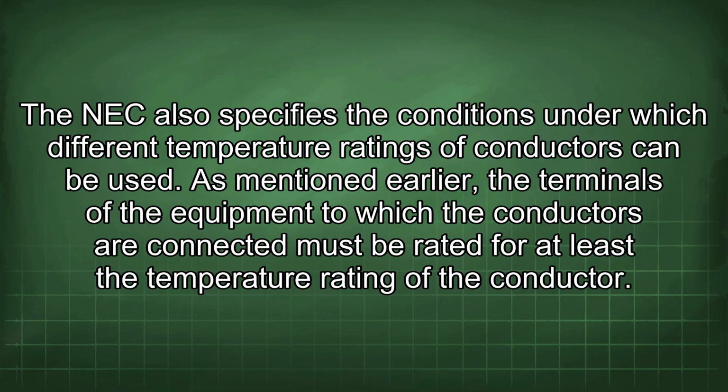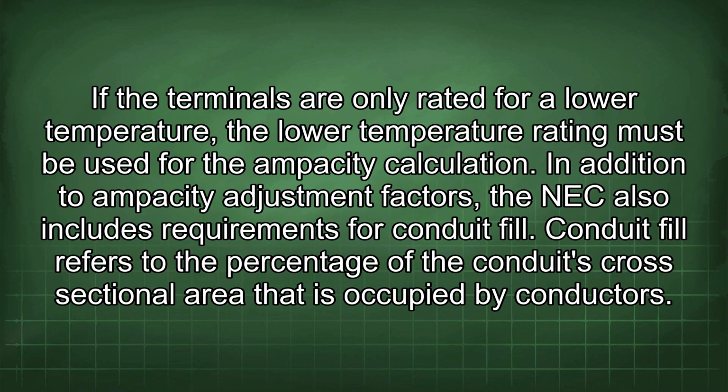As mentioned earlier, the terminals of the equipment to which the conductors are connected must be rated for at least the temperature rating of the conductor. If the terminals are only rated for a lower temperature, the lower temperature rating must be used for the ampacity calculation. In addition to ampacity adjustment factors, the NEC also includes requirements for conduit fill.